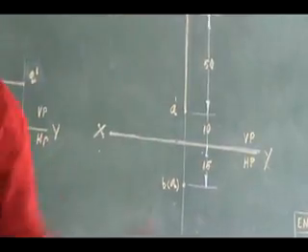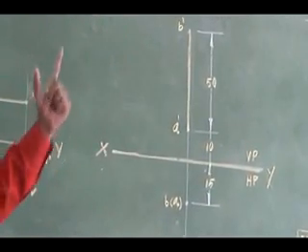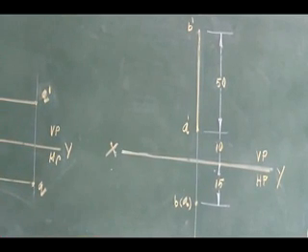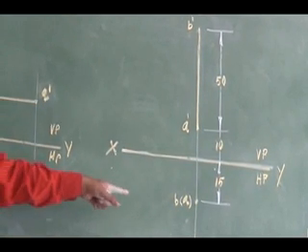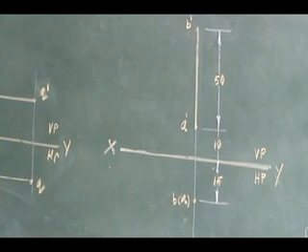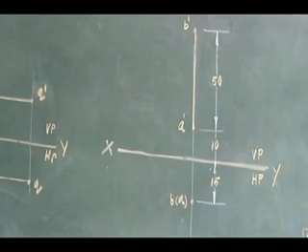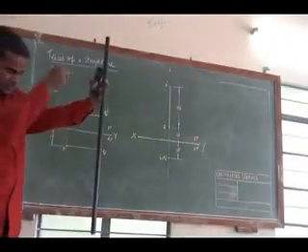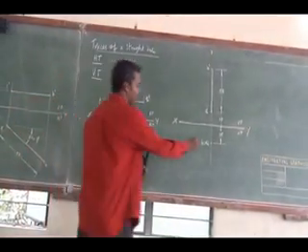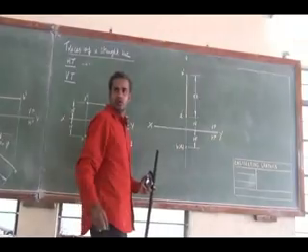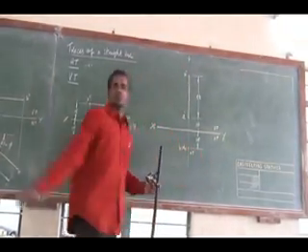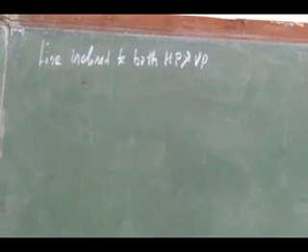It is like this. Okay, vertical: parallel to VP and perpendicular to HP. Do you have a trace? What trace will you have here? HT. Right. It is like this. I can extend it and it will meet the horizontal plane, wherever I have my top view. That is the location of my horizontal trace. These are the problems you will be getting in this case.